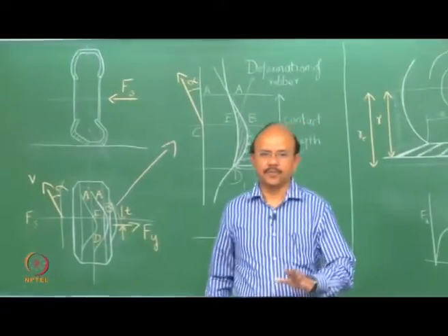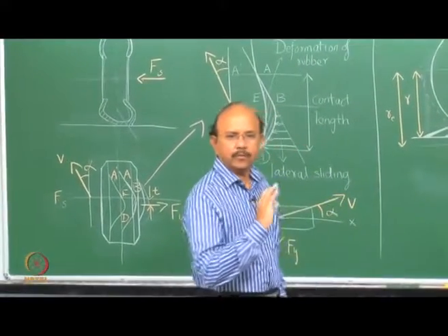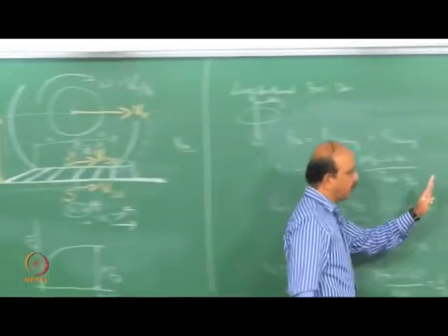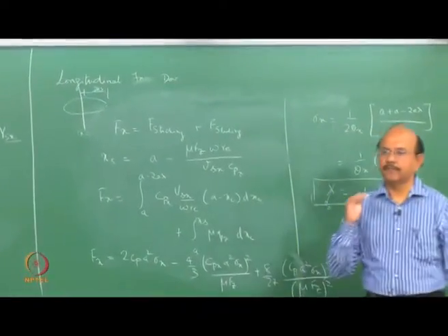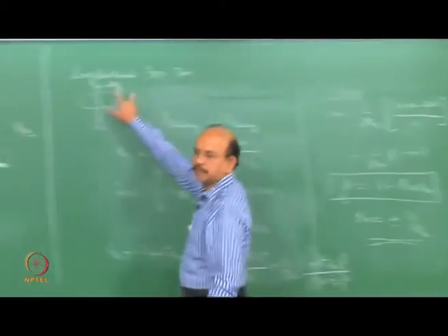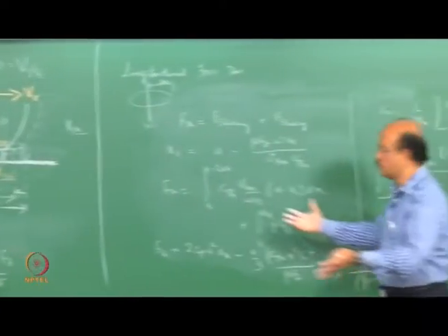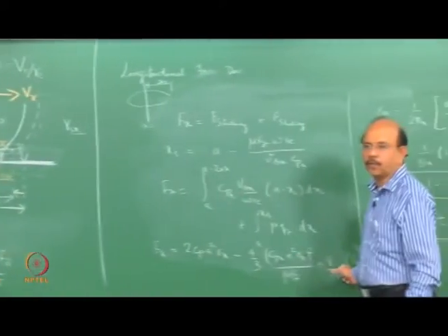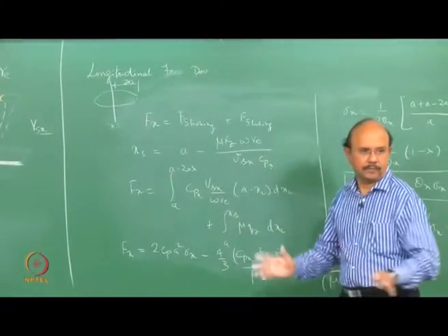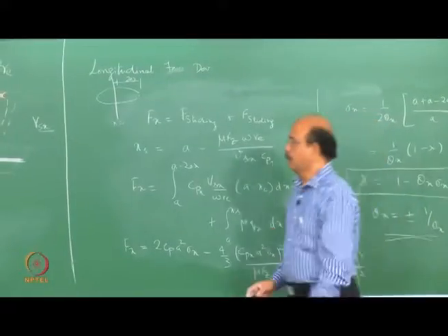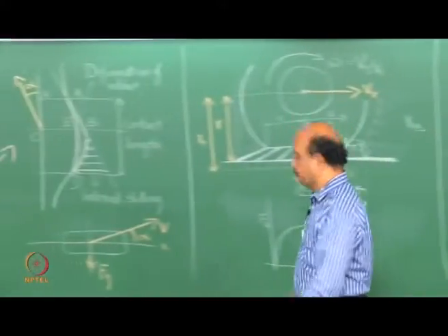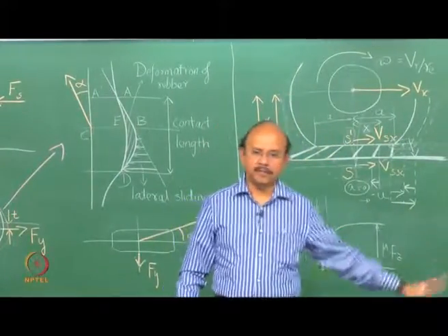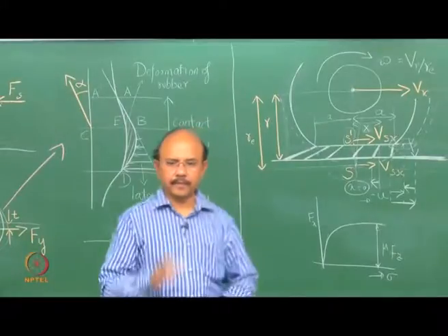Okay. So essentially, this is a brush model, where we found out the deformations, we found out where the sliding takes place, the place where the sliding happens, and we just found out the force due to just deformation and due to sliding, and then we wrote down a complete final expression, period. Look at that. This is slightly different from what's given in Pacejka as an expression, but I think this is correct. Have a look at it.